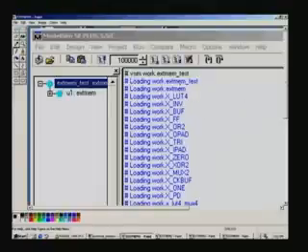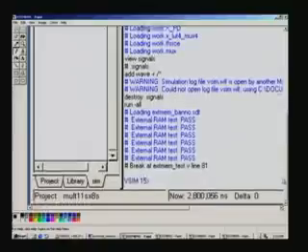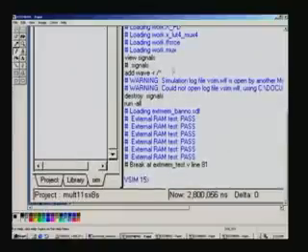So we have taken the back annotated file, and that is why loading shows all the primitives there. And finally, we have run the actual process, and it ran that external memory back annotated file and reported that the test is a pass. That means all the 65,535 locations have been successfully written into and read back. This is with only data 555. You can experiment with other data.